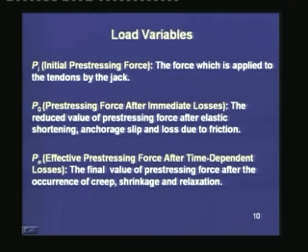The second one is P0, which is the prestressing force after immediate losses. That means the actual prestressing force that is transferred to the concrete section is lower than the value which is recorded by the gauge in the jack. It is lower because of the immediate losses of elastic shortening, friction and sitting of the anchorage, and that we shall denote as P0.